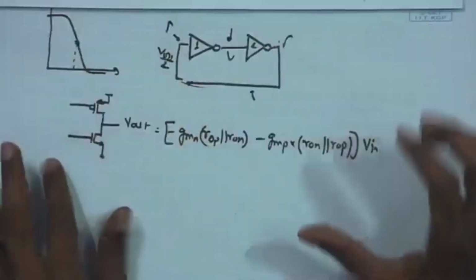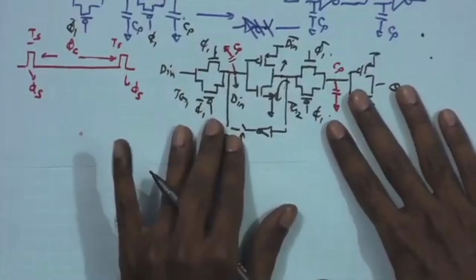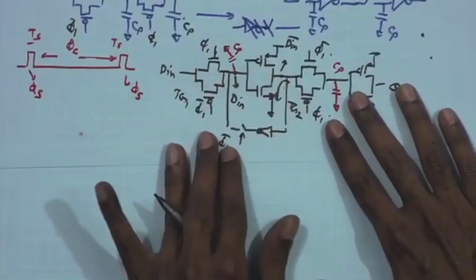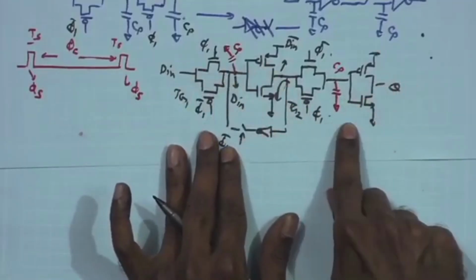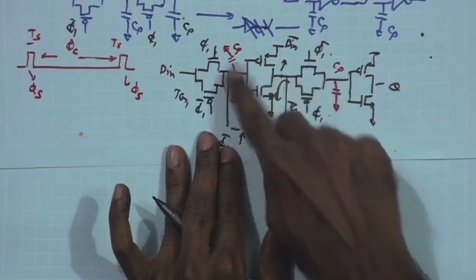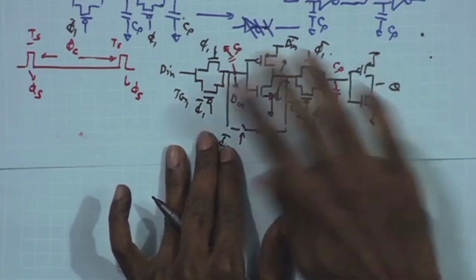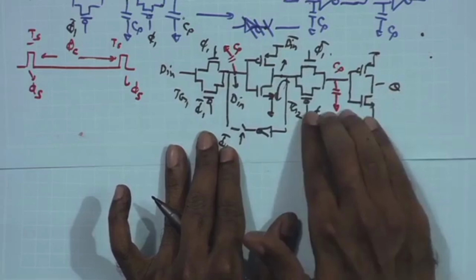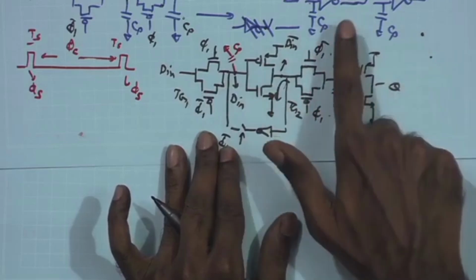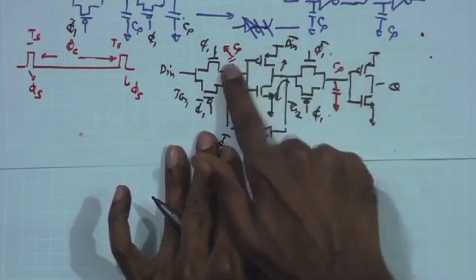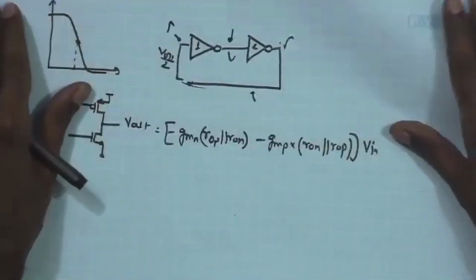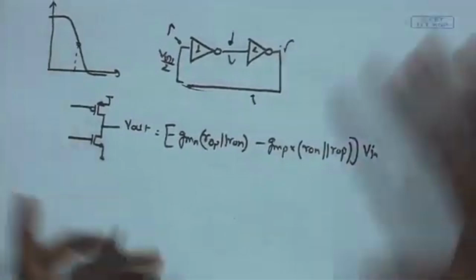So, my final implementation of the flip flop considering this topology would include just another inverter over here along with the switch, and hence creating two latches which have the positive feedback path activated at the complementary phase of the clocks. So, I can complete the overall latch, the flip flop circuitry.